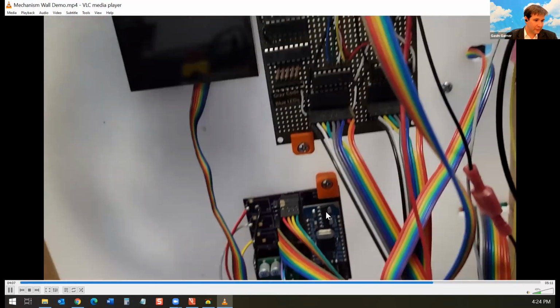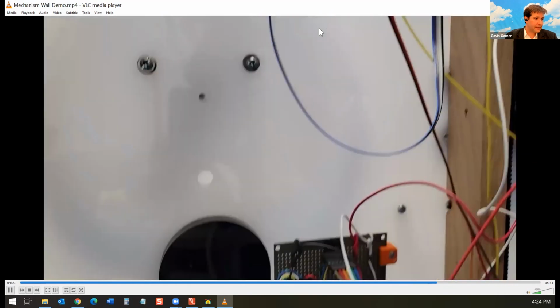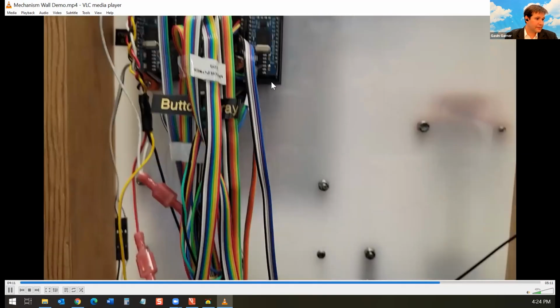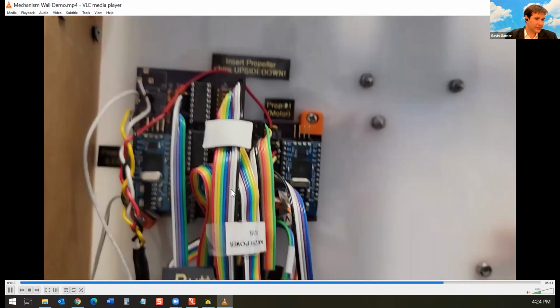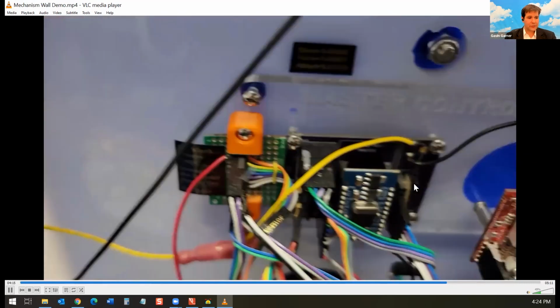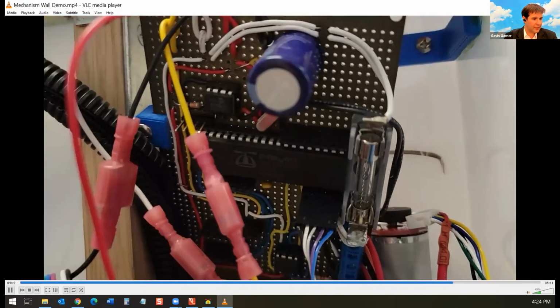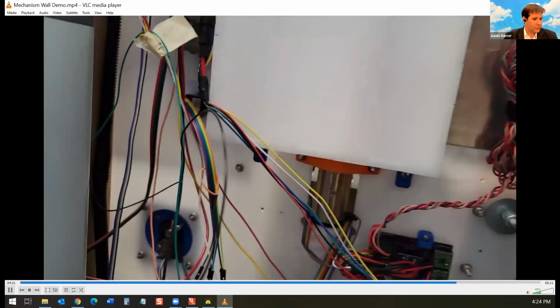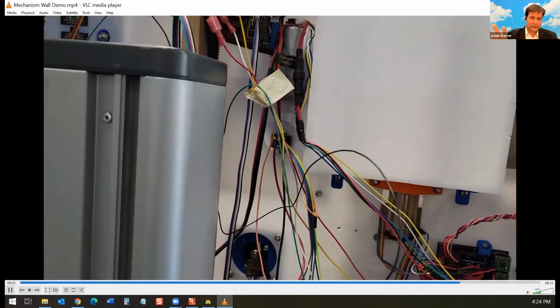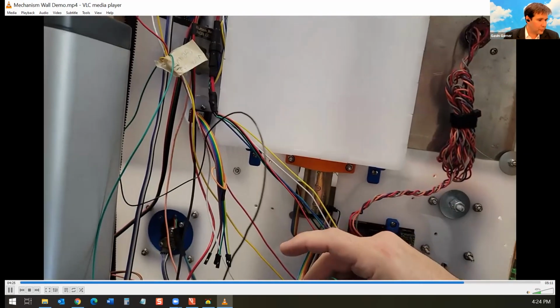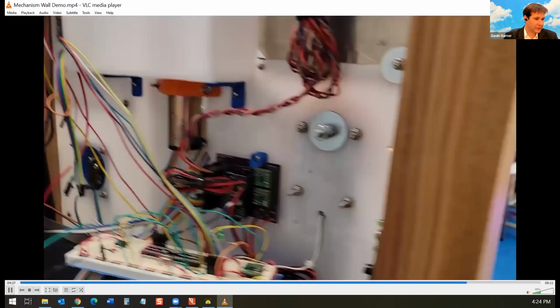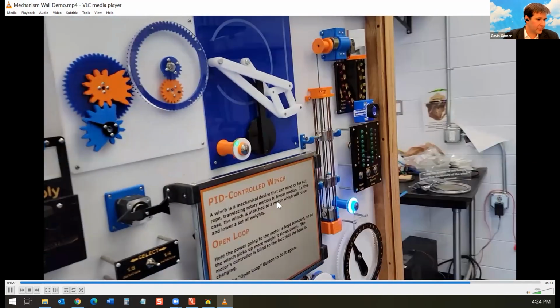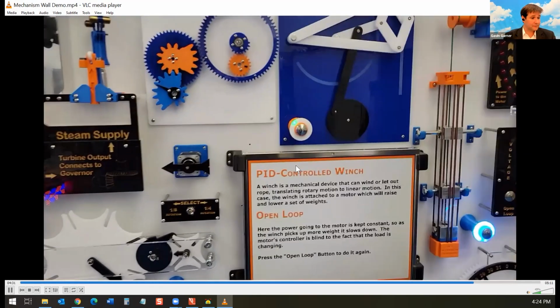You can see a Propeller Mini there. We've got two Propeller Minis on this section. There's a bunch of Propellers, and I had different students take on different parts of these, and each one was controlled by its own Propeller chip. Then we just sent out a 4-bit system to tell it what mode to do at any point in time. So we kind of cheated and just did a quick parallel, one-way interface so that the master controller can tell it which ones to operate.